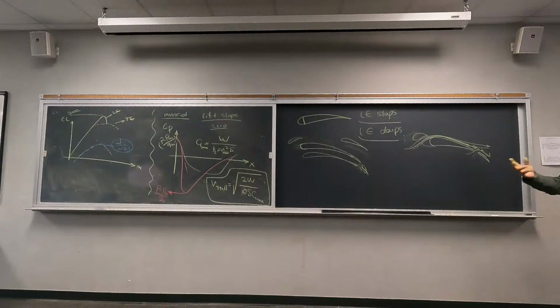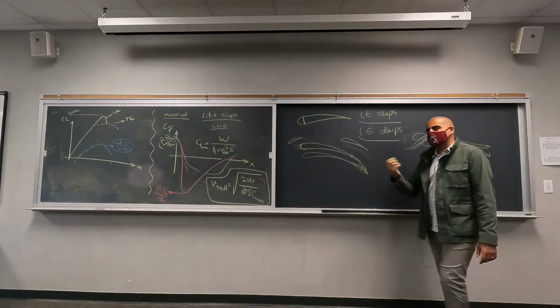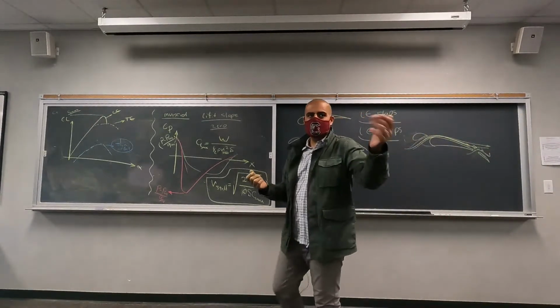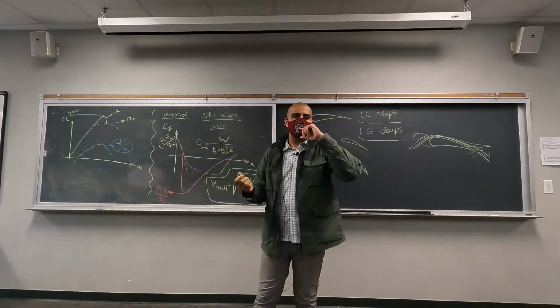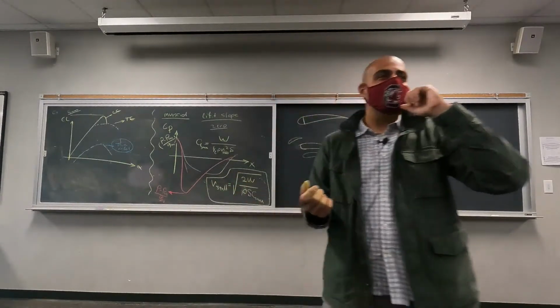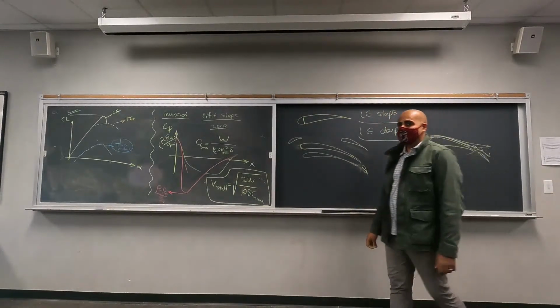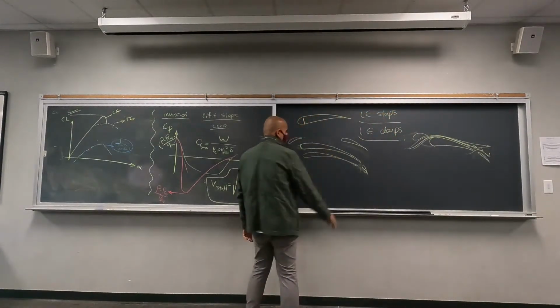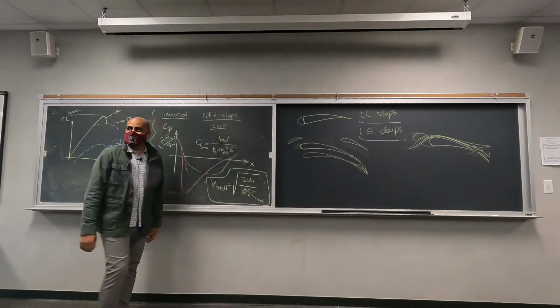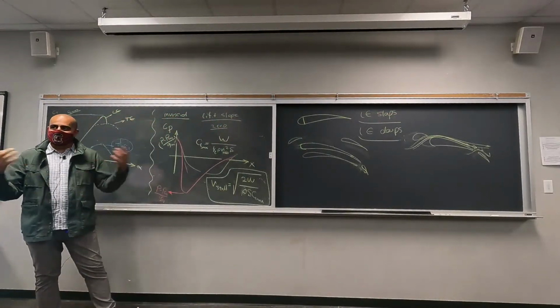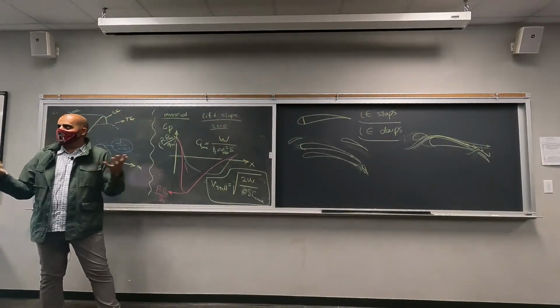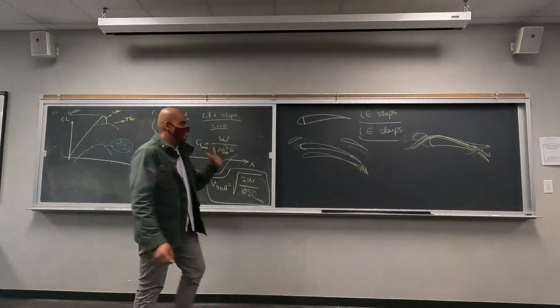There are other mechanisms. This is worth mentioning as well. This is something that some people did research with, like the dielectric barrier discharge. That, what was your name? Ben. Yeah, Ben brought that up. That's something that you can definitely have. You're going to ionize the gas on top, which is going to introduce an electric field in the system. That's an extra source in the Navier-Stokes equation, an extra force going to push the flow down.